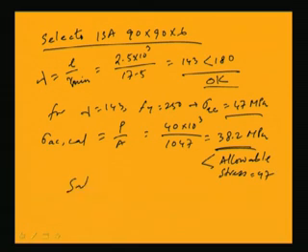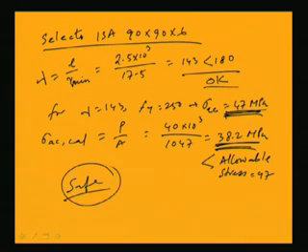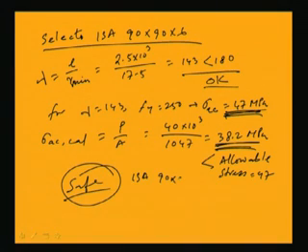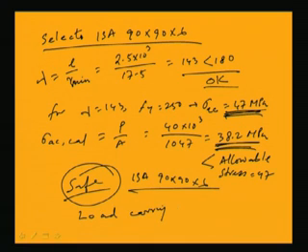So, the design is safe, okay, because developed compressive stress is coming 38.2 and allowable stress for this particular member is 47 MPa. So, the member is safe. So, we can say that ISA 90 by 90 by 6 can be provided, okay, for this type of connections, right. Now, here load carrying capacity is becoming how much?